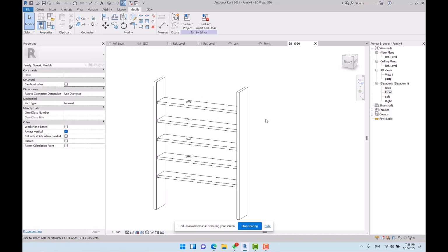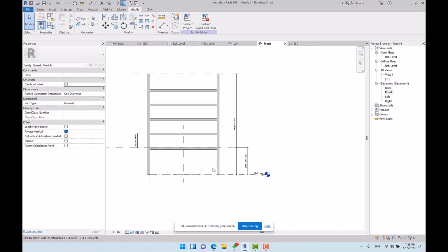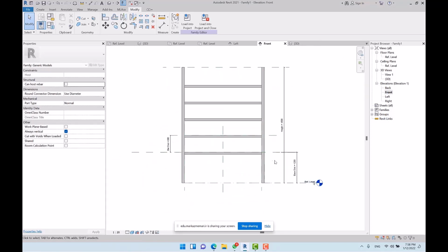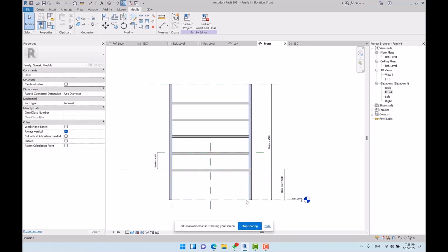So during this process, I taught you how to array the panels, or in other words, how to duplicate them by using the array tool in two ways. Firstly, you can use array by using the ordinary tools like move to second and move to last. And in the second approach, I created some parameters, for example distance, base distance and between distance, in order to control the number of the panels.